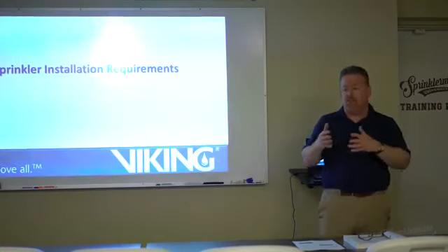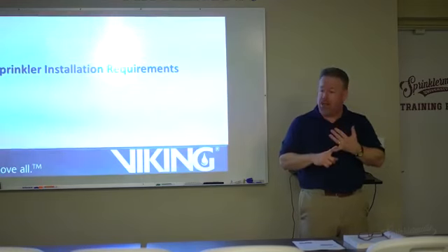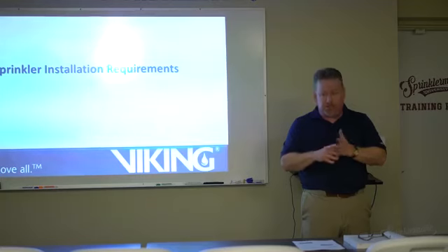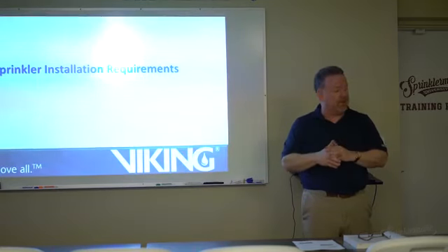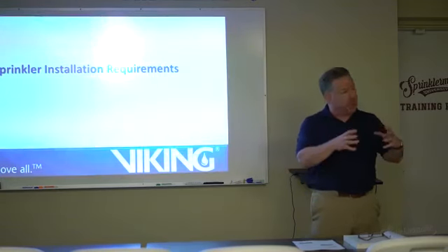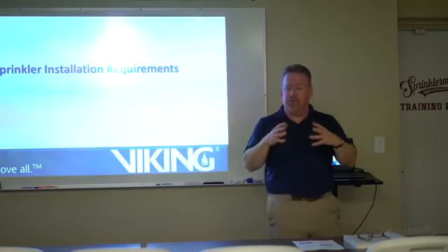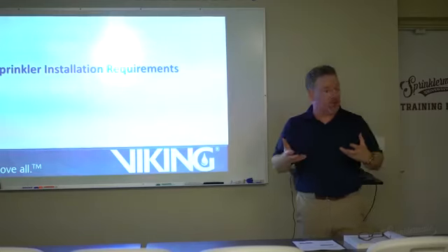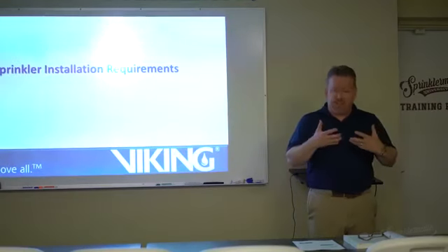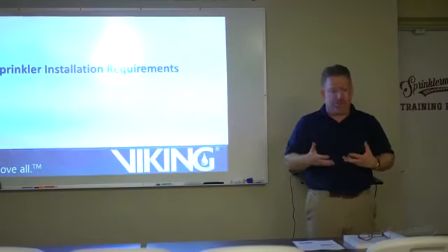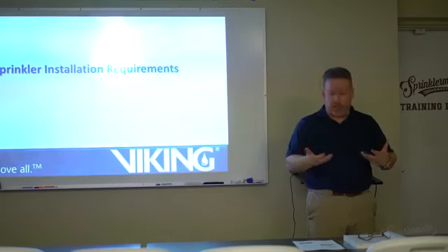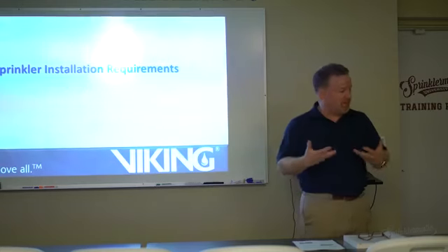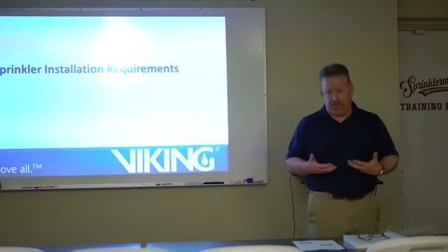Because in some cases, it's going to drive what type of sprinkler you can use. It's going to limit the area of operation or provide some area of operation guidance. So it's really important to get the classification of the occupancy correct. That is the single most important decision that a designer, a layout technician, or an engineer is going to make: identifying the hazard classification for that building.